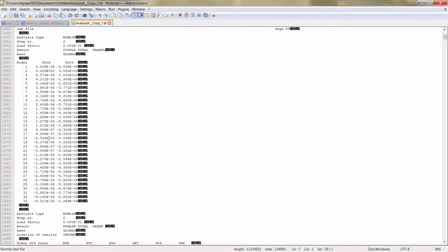So the good thing of this TB file is if you configure in the output like 1,000,000 or 2,000,000 lines, you will get the same pattern of the results. So you can just develop your own script in MATLAB, Python, or Excel file to get the results in the nodes and or in the elements that you want, just by following the line order.